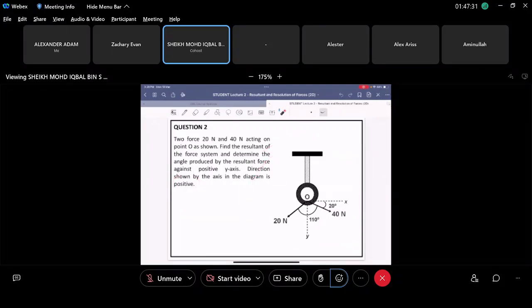So you can see this is the figure here. What should we do first when we encounter a problem like this? Anyone? Hello? Anyone know what is the first step to do here? Yes, we have to draw the free body diagram. Because without the free body diagram, you will get confused, right? So it's better for you to set your state of mind now, in these earlier chapters, that for every figure and every applied mechanics problem that you see, you draw a free body diagram first, right?